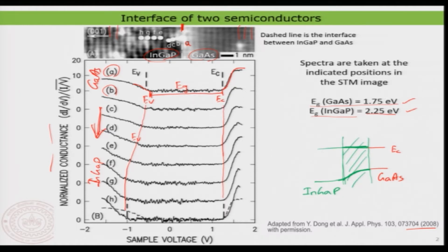Yeah, this is quite important, because when you want to construct an interface, you want to also think about a device which is more hole conducting or electron conducting or whatsoever, then this band alignment is quite an important aspect to consider, for example. Yeah. Now, for example, if I want to transport electrons in this, you can see that their bands are aligned. So, there is almost no barrier for the electrons to move from one type of semiconductor to the other type of semiconductor. So, that is basically the point. So, here when I am talking about electrons, it is the so called electrons that are present in the conduction band. Yeah. So, like that we can think about.